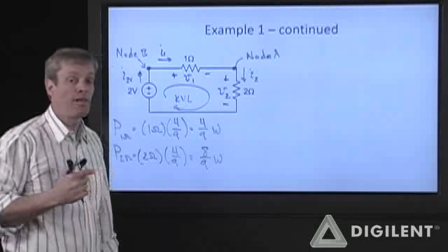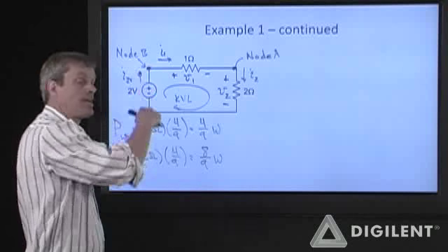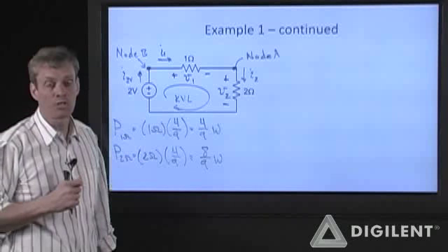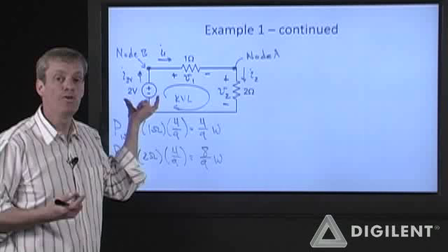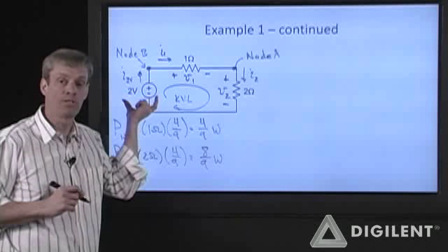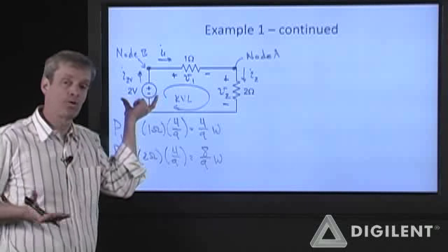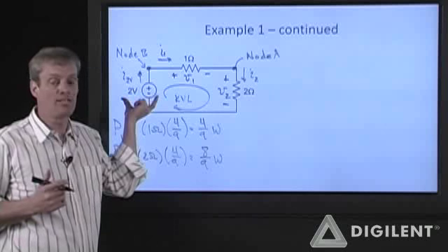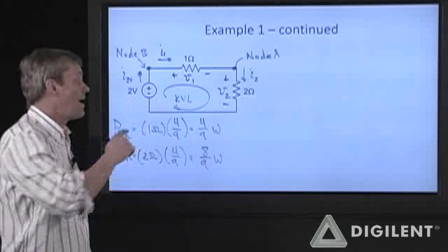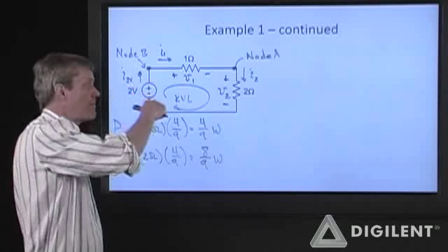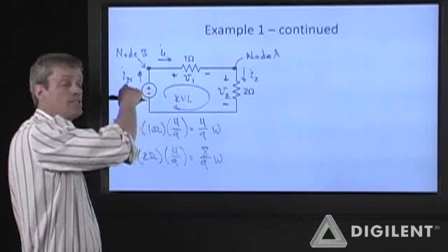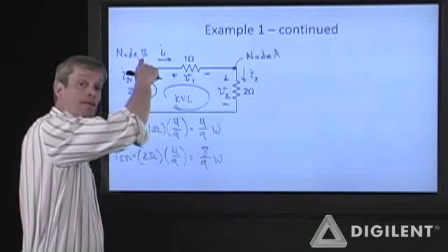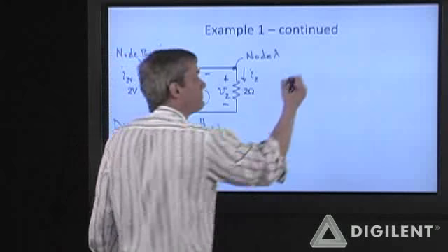In general, applying KCL at either the inlet or outlet of a voltage source is not going to help you because you know nothing about the current through a voltage source. Remember, an ideal voltage source can have any current that it needs going through it. However, to get this power from this guy, we need to determine the current. Now KCL at node B helps us out.